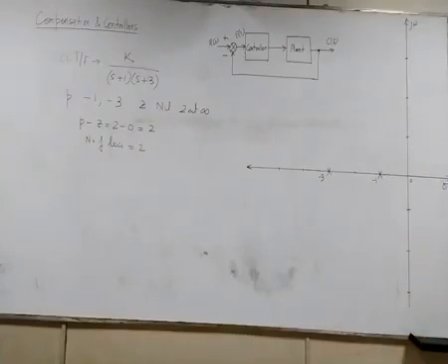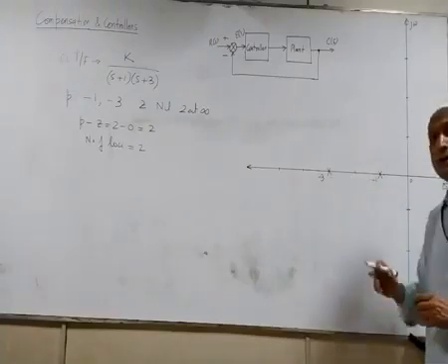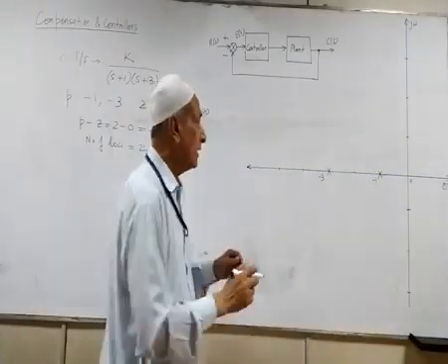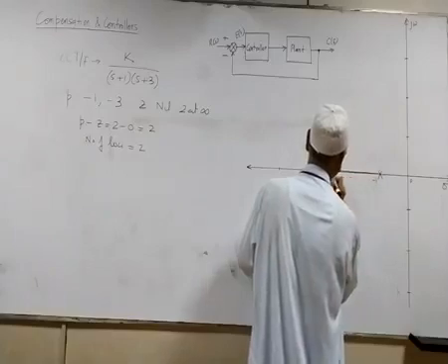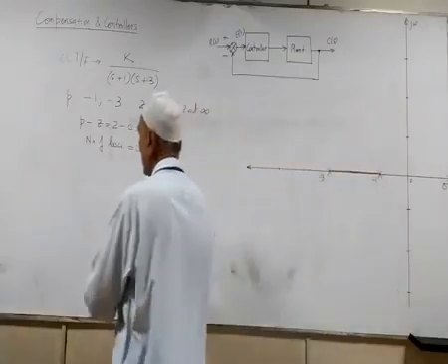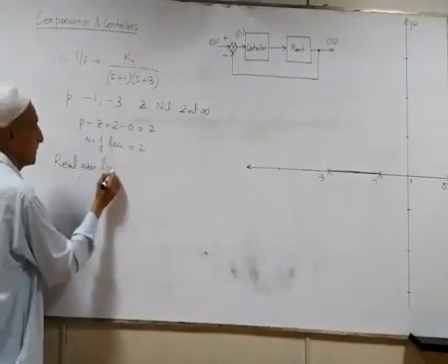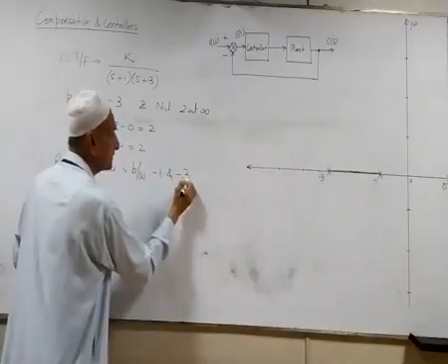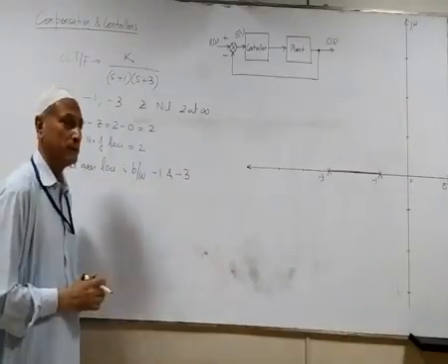Now comes the question of the real axis loci. There is no zero, so we have 2 immediately adjacent open loop poles. So there is a real axis locus lying between these 2, that is, between -1 and -3. Now this means that we must have one breakaway point.